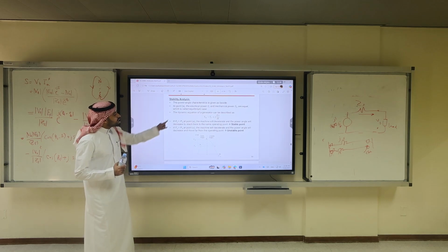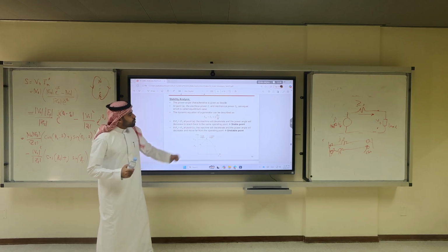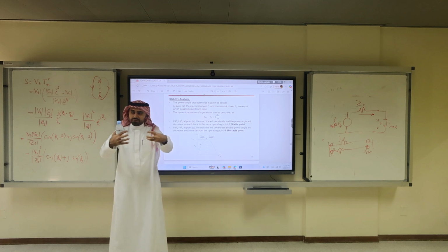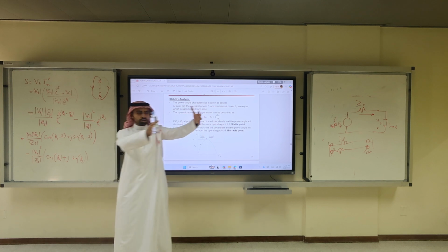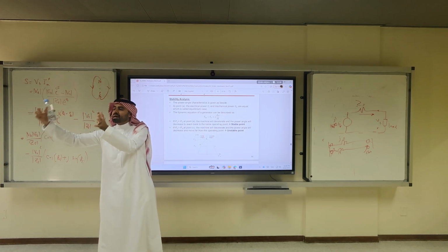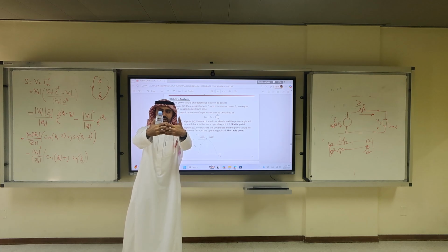It turned out there is a dynamic equation, which we call the swing equation, where the difference between the electrical torque and the mechanical torque in the shaft, in the coupling, matters. The synchronous generator is the electric machine, there is the prime mover, which is a mechanical engine, there is a shaft connected, a coupling between them.